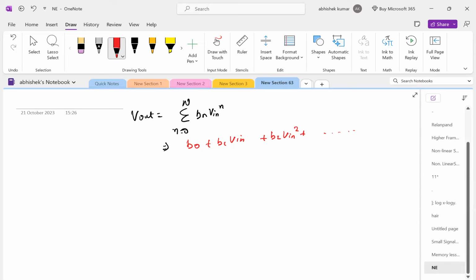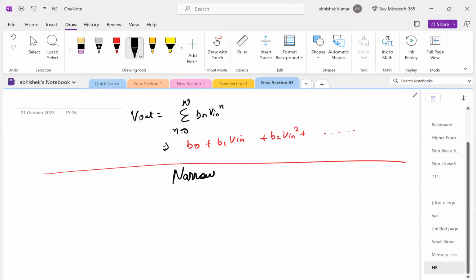Okay. No. Then we have a narrowband system. In our wireless communication system, we are concentrating on the narrowband system. What is narrowband? Narrowband means that the beam that we are sending is very narrow. In a typical wireless transmitter, you can see many RF systems have relatively narrow bandwidth, that is, the signal bandwidth is small compared to the center frequency.